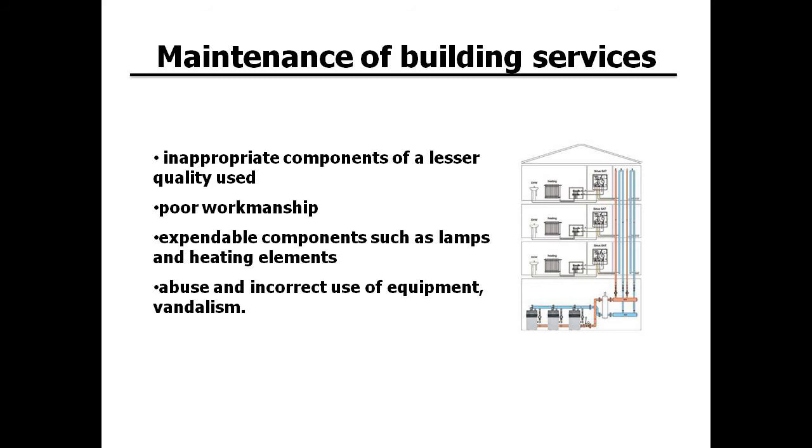So that's important to look ahead in the design. A good preventative maintenance program, extremely important. The services need to be sympathetic to the environment, understand what location the cooling towers are going to be working in. So is it coastal, industrial? Is it heavily treed? Is it a highly acidic environment? And with the service and the level of services that's going to be required.